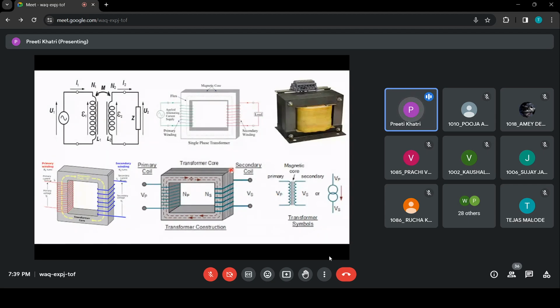Or in a simple form, we can say that in a transformer there are two circuits present or two inductive coils are present which are magnetically linked but they are electrically separated. Means what? They are magnetically linked with a path of low reluctance as it is shown in this figure if you see the color notation, and they are electrically separated because there is no relation between the electrical parameter of one side and the electrical parameter of the second side there.